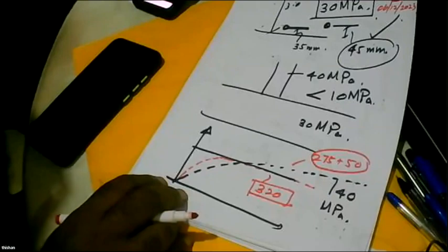Okay, now you can see when you use fly ash based concrete, it's good to continue the curing at least for 14 days, so that over the 14 days, all tricalcium silicate will react, form a lot of calcium hydroxide and calcium silicate gel, and create a strong concrete.